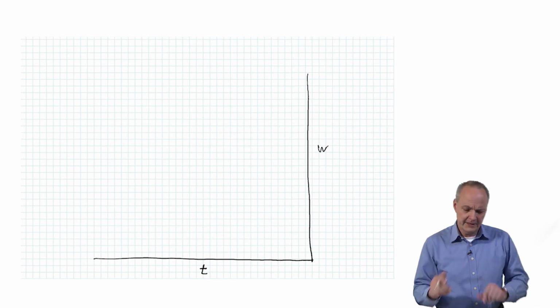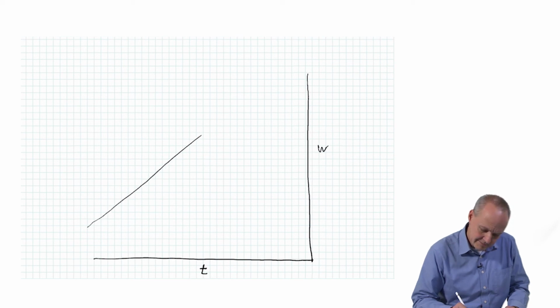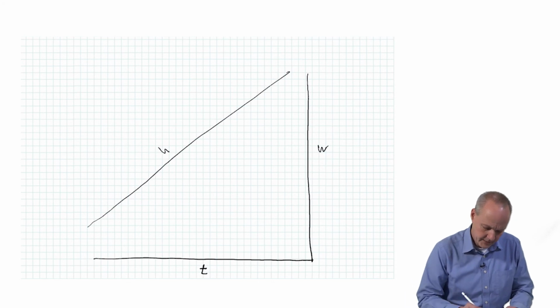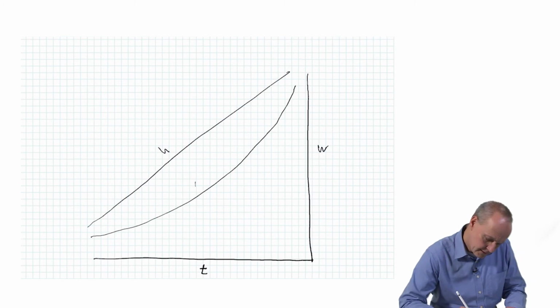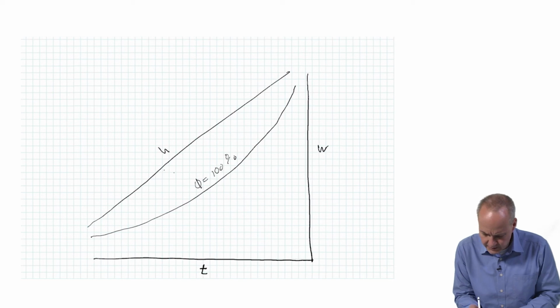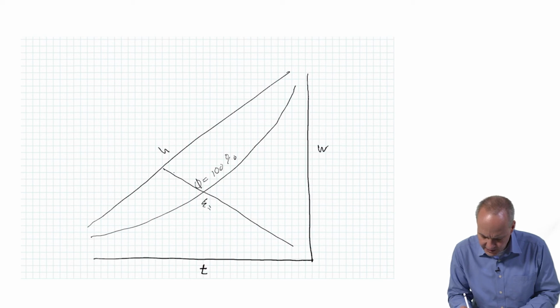There's some slight variation from linear. The real second linear variable in the psychrometric chart is actually the enthalpy, which was up here, with an axis here. And remember, we had the saturation line, phi equal 100%, up here. We have lines of constant enthalpy and constant wet bulb temperature, and they look something like this, H equal constant.